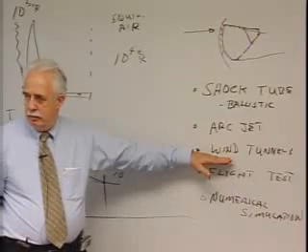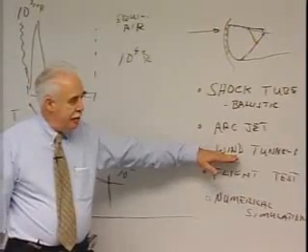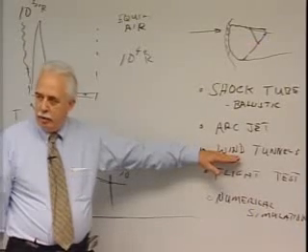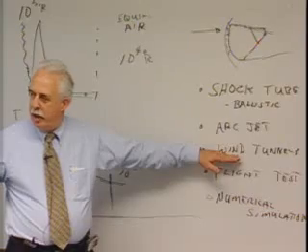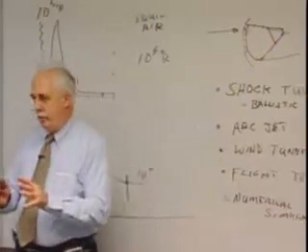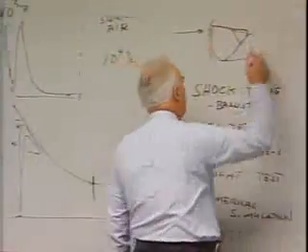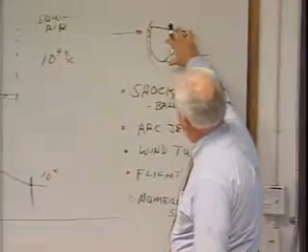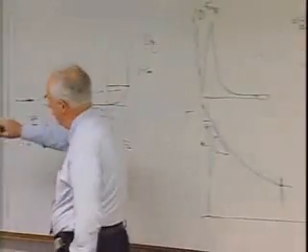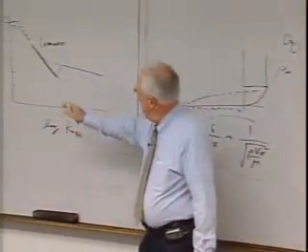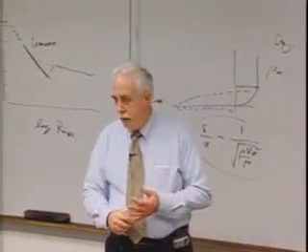Before we flew, in regions of the vehicle, I made statements which I still would make. We could compute the heating on a wind tunnel model about as accurately as you could measure it in regions, not over the entire region, not over the separated region, not over conditions where the flow was turbulent. But in the laminar environment, we could compute it as well as you could measure it.